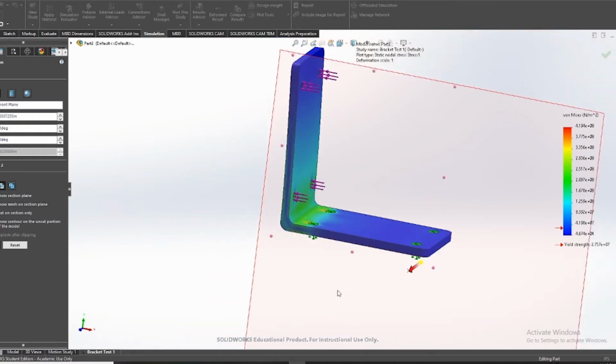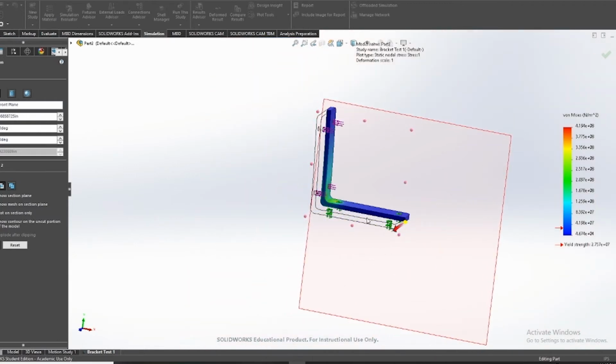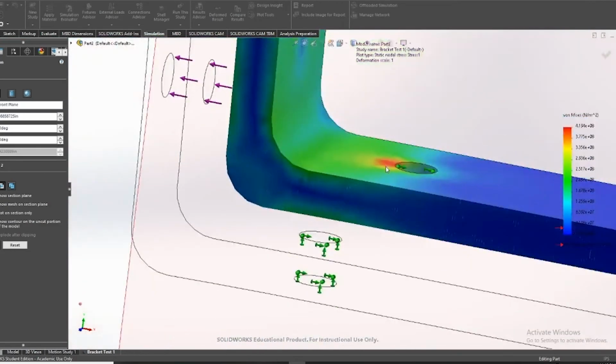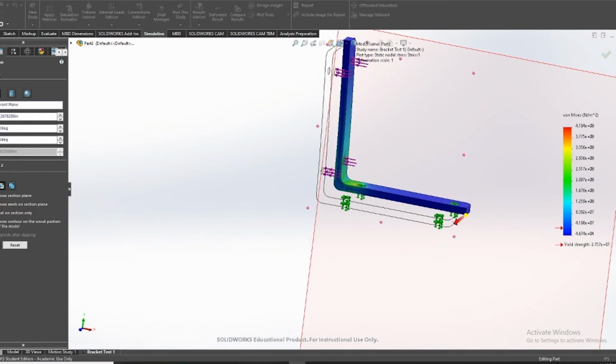So this is really good for determining which parts of your part are the actual issue, because clearly here it's not the inside, it's outside loads. So you don't really need just a stronger material, you need better bracing on the outside.